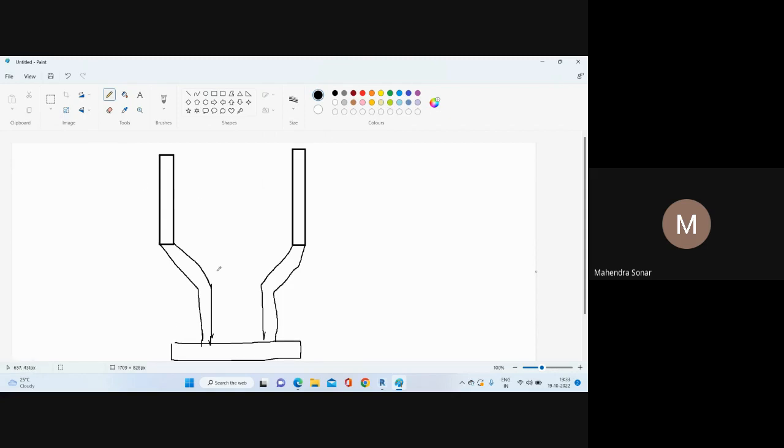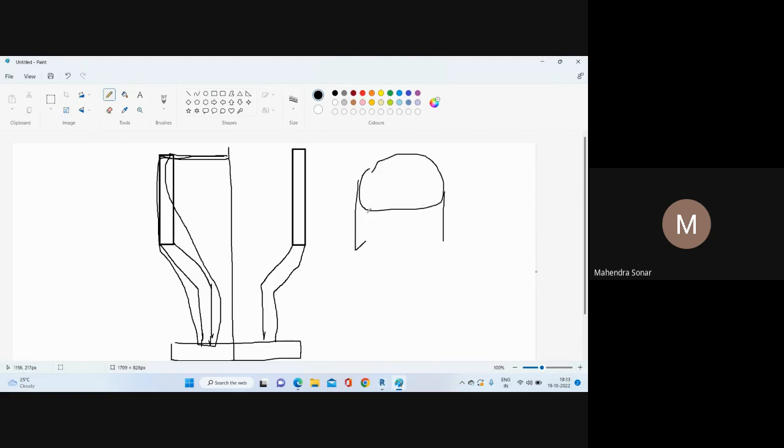In that case, what we need to do is first give an axis line here. So this is your axis line, and after that you just create half of the structure, half part of the structure. So you just need to draw this shape here. Once you draw it, this shape will be revolved 360 degrees, so you can create this type of structure, because we don't have any other command here for creating this type of shape. If you look at the 3D view, it looks like so.